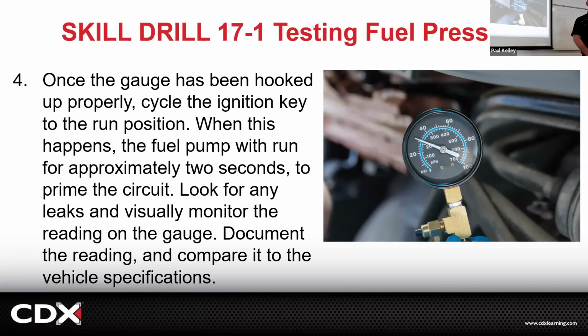I've also seen where the fuel pump has a problem with the motor, where everything is cool and everything is good, but then once in a while the car will die. You'd be driving, and then all of a sudden stumble, die. You're like, did the fuel pump just die out? How would you know? Hook the fuel pressure gauge up to it, tuck it up under the hood, tape it to the windshield, drive around. If the car stumbles and stalls and you look and your pressure's still 50 psi, it wasn't the fuel pump.